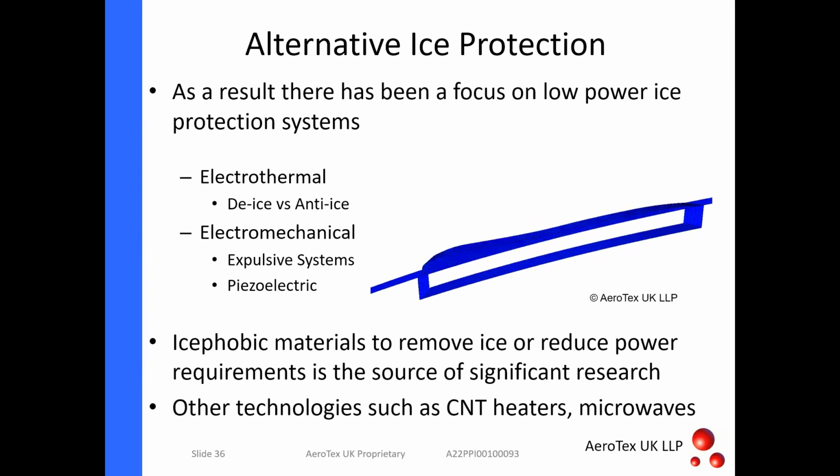I spent 5 weeks out there. We had a spin rig that we accreted ice on and it shed it. But I feel that there's some stochastics needed in there, because we could test the same specimen in the same conditions and the adhesive property would vary by maybe up to 200, 300%. It's these fundamental properties of ice that we're particularly interested in, because if we're going to go low power, we need to understand this better.